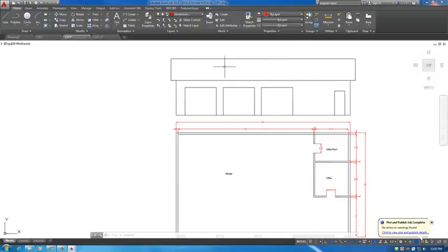Remember, there's a whole lot more involved with architectural design besides just getting the dimensions right. Architectural design involves calculating snow load and what type of roof pitch you should have based on your snow load. What is suitable here in Wisconsin may not be suitable for, let's say, the Rocky Mountains in Colorado. You might have to have a steeper roof pitch because there's so much more snow. The lower the roof pitch, the more effect the weight of snow has on the roof itself.